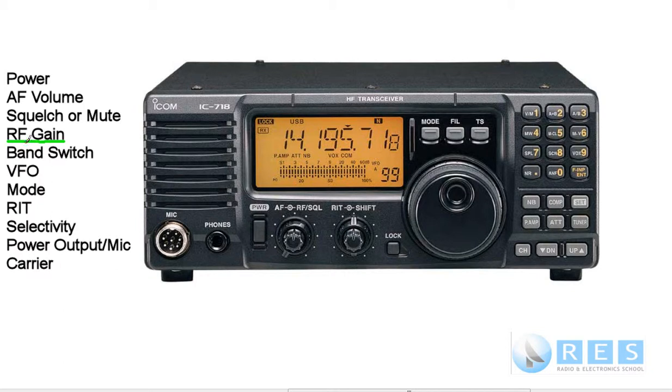If you're receiving strong signals, you don't want the RF gain up very high. If you're receiving weak signals, you want it up very high. If you're checking to see if a frequency is in use, you should turn the RF gain up very high to make sure your receiver in your transceiver is set to maximum sensitivity.